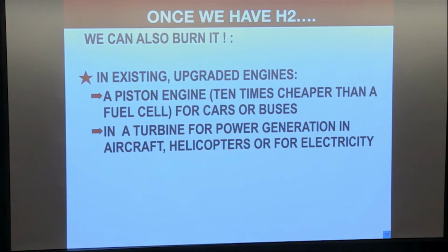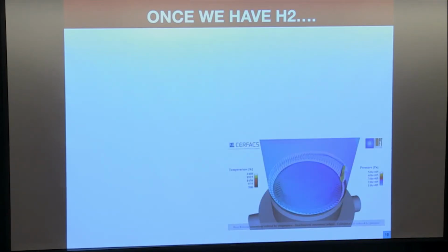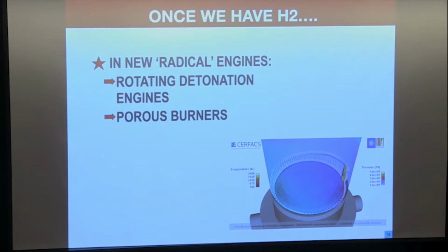But you can also do things which are a little bit more radical, like the one I've shown you for RDEs. You can imagine new engines with rotating detonation engines, for example, because it's kind of difficult to make kerosene detonate. But if now I tell you, you get all this H2, combustion experts will say, oh, that's nice, maybe I can use it to do a different engine. And RDE, of course, would be one solution. Porous burners is also an exciting solution to use H2. And that's, again, your new science for you guys to develop.